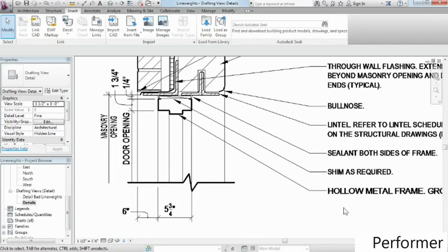So you can get desirable and predictable results on the files that you import into Revit, either by using the line weight feature from CAD first and Revit will read it directly, or by building a color mapping table to establish all the line weights ahead of time so that when it gets imported in, they will map correctly to your desired Office standard.